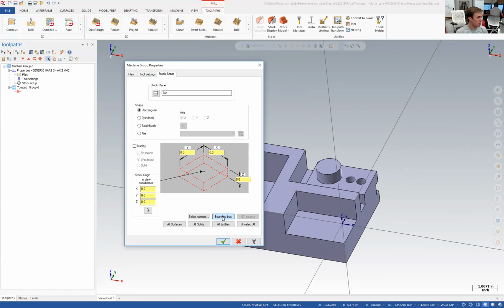Now say that I know I don't have a radius of 3.6. I actually have a, let's say a 7-inch round. So, well, no, a little bigger, 7.5-inch round. That would be this radius. You can update it. Another way to do that is to click on the surface of this part. Say I want to surface the top off. I would grab it and pull it up, maybe 100 thou. So now I have a little extra stock to work with, and I can face it down before I cut my part.